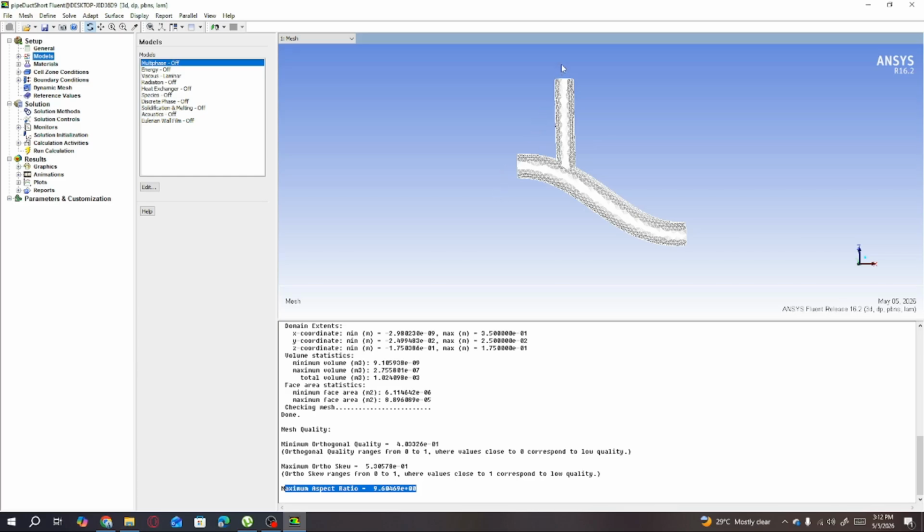So again, both will mix up here, and there certainly the temperature changes occur, and on the basis of that, certain energy transformation takes place within our process. So considering this scenario, we are going to turn on this energy equation, okay, and by double clicking you can select it, and you just need to check the option to turn it on, okay.